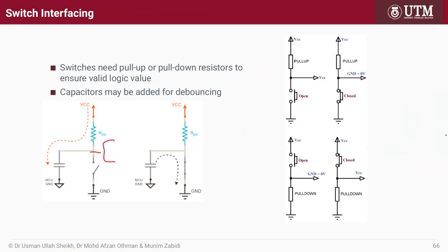The MCU is over here. Okay, the controller is over here. So if I press here, the value will be 0. If I don't press, I will have 1 here, because the value cannot go to ground, and through a resistor actually there's not much, so actually it should be here. So this is active low. Press becomes 0, no press becomes 1. And the capacitor here is for the bouncing, so that you don't have so much glitch.